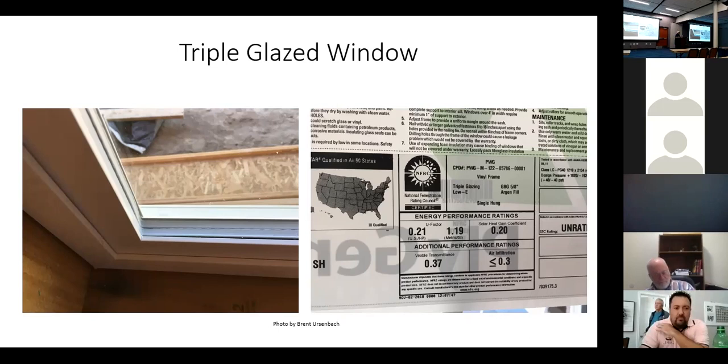We don't have a requirement in our climate zone, but in climate zone 3, Washington County, we have a requirement for that. But we definitely want to consider it, and our HVAC guys have to consider it. And really, if you have a lot of west glass, you will not be comfortable unless you provide some type of ability to shade that glass.